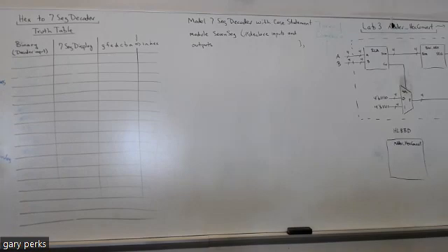However, the LEDs, when they're biased, so current flows through them, wouldn't light very brightly. They'd be kind of dim. And that's because what this is connected to doesn't quite have enough current capability.